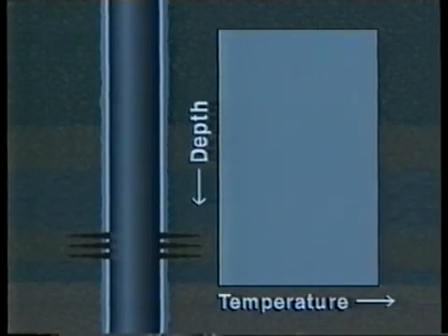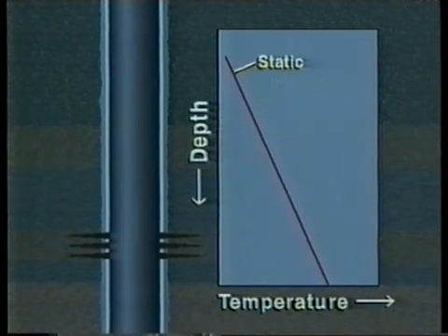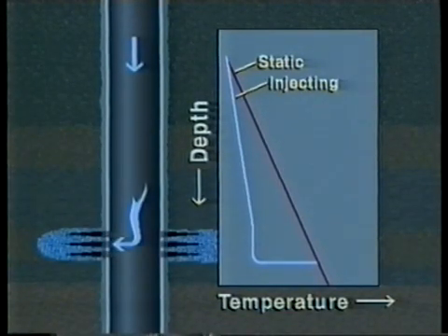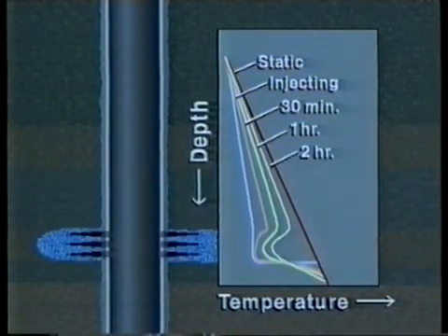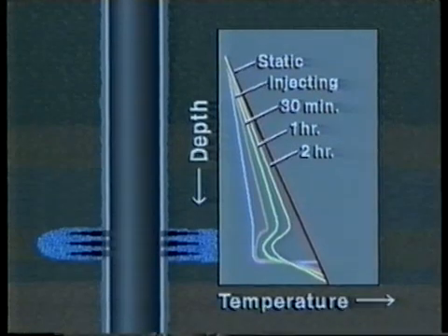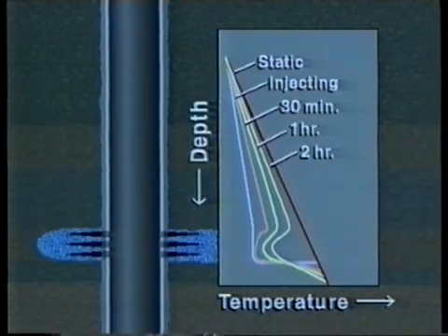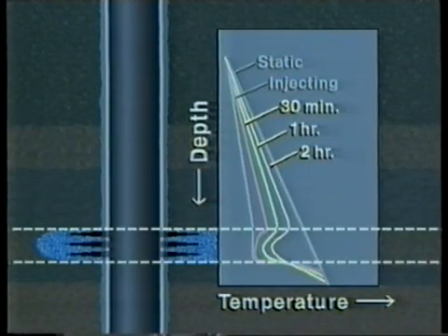Temperature surveys are also used in injection wells to identify the intervals taking fluid. The technique entails running a pre-injection base survey, running a temperature survey while injecting the cooler surface liquid, shutting in the well, and then running a number of temperature surveys during shut-in. The volume of injection fluid left in the wellbore after shut-in will return to the geothermal temperature relatively rapidly, while the large volume of injected fluid held in the zone of injection will warm to the geothermal temperature much more slowly. As a result, the shut-in temperature surveys develop a bump across the injection zone, highlighting its extent.